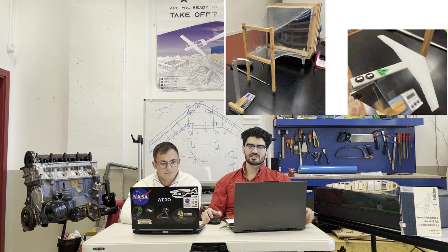First, we'll cover the experimental section of this study. We started the analysis by testing a scale model of the flying wing in an open wind tunnel. To simulate incompressible flow, we used a relatively low speed regime where the Mach number was pretty much zero. We're talking about a 10 meters per second constant airspeed. As you'll see now, however, it was far from constant.